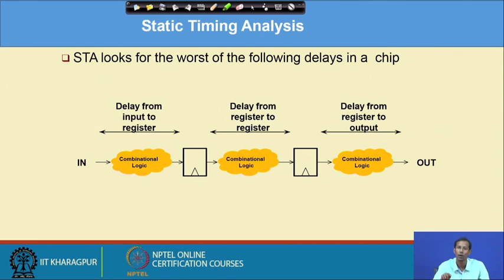So now it is dependent on the clock, not on the data. In a combinatorial circuit, if you change any signal, it automatically reflects at the output. But in a sequential element, if you find the edge, then it checks the value present at the data, and based on that data the output will change.